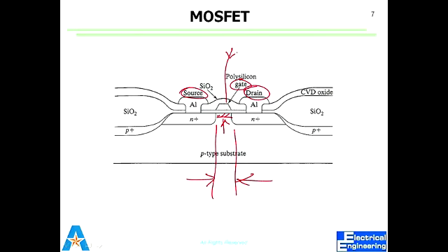So negative charge carriers will accumulate in that region because of attraction to the positive charge. They're spread around, so they will accumulate. But it's a p-type device, so those charge carriers, which are electrons in this case, are they minority carriers or majority carriers? But its substrate, the bulk, is p-type, right? So they're minority carriers. There are few. It's a p-type material, which means there are many more holes available, but there are some electrons available. So we attract those few electrons to come close to that surface.